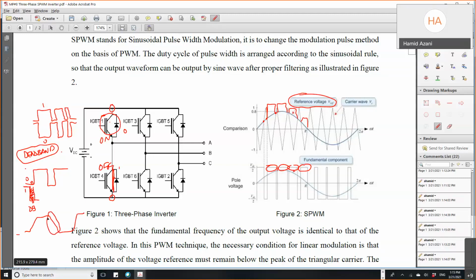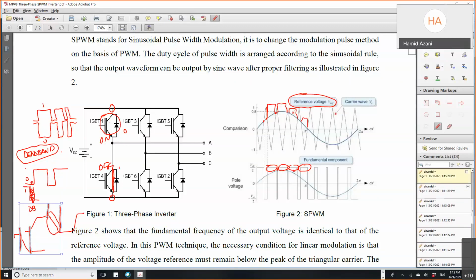We have to give that time to this one here before we switch the other one on. We give it a time to discharge, and after that, we'll be sure that this one is off, closed, I mean, not conducting. That time you can make the other one on, and so on.